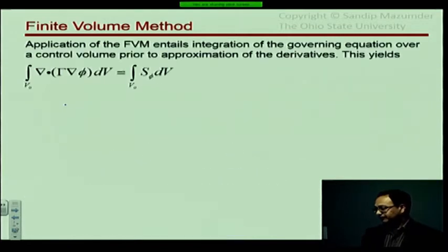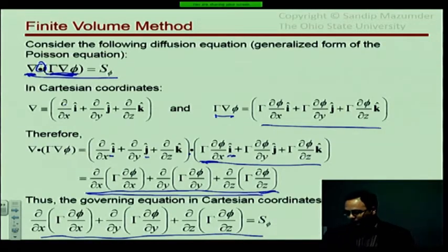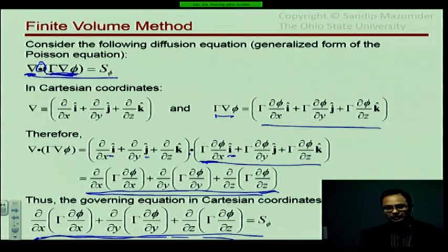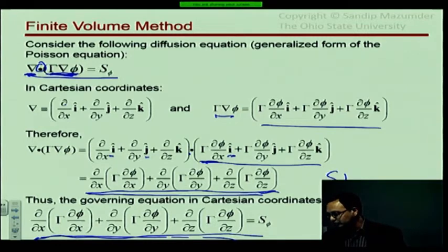All right. So, in the finite volume method, right away, big difference with finite difference. In finite difference, what we would have done is we would have taken this equation straight away, applied Taylor series expansions, and approximated those derivatives. That's what we did all along. Our central difference formula gave us approximations to those derivatives, and that is why when we do finite difference solution, it is known as the strong form solution.